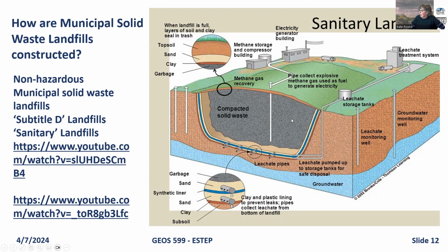What we're looking at is a sanitary landfill that has effectively been closed down, but it still gets monitored. So remember those pipes I was talking about? They all feed to what we call leachate storage tanks. And those leachate storage tanks send the leachate to a leachate treatment system. And that treatment system basically extracts pollutants, and exactly how this works varies, but it puts the clean water back into the natural setting.